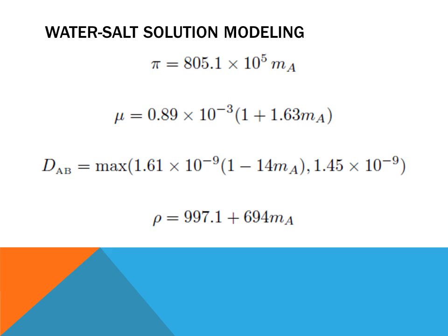What this in effect does is create a weakly compressible case. This mass fraction is not going to cause the molecules of water to move closer or farther together. The flow is still going to be incompressible. But we have to instantiate flow change due to this mass fraction, so it's known as weak compressibility.